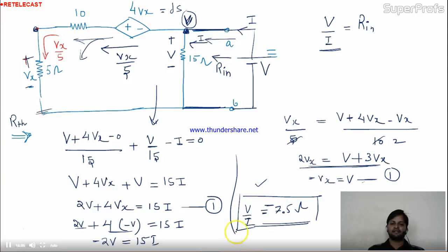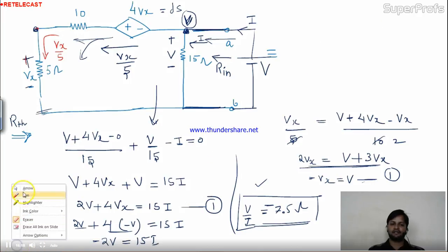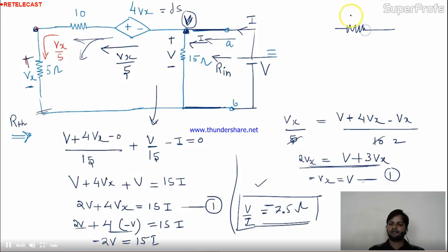Please check it. So in your resultant network we have to show the Thevenin equivalent voltage in series with resistance. The resistance is 7.5. This is the terminal given, A and B. Here the voltage is 0 volt.